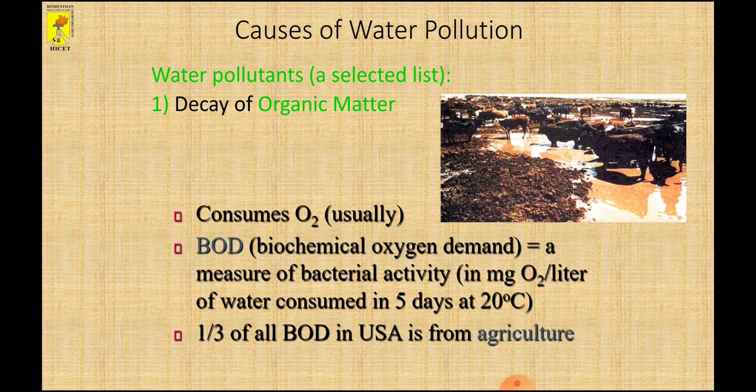Dissolved oxygen is the amount of oxygen dissolved in a given quantity of water at a particular pressure and temperature. It serves as a means of control of river pollution. A minimum level of dissolved oxygen, 4 milligram per liter, must be maintained in rivers so as to support aquatic life in healthy condition.